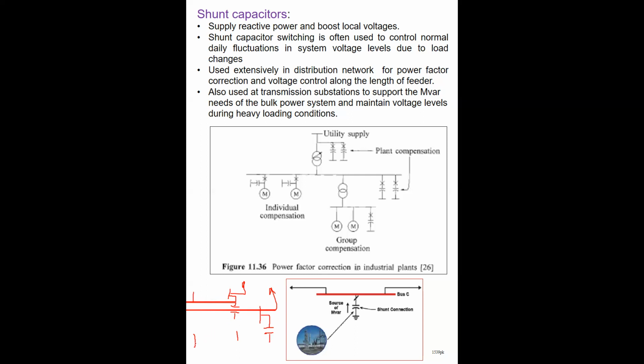For example, if you connect your capacitor here, but your load is here, and you want to improve the voltage at this bus where you have the load connected, with a capacitor connected here, then there is a transmission network connection in between. Then this capacitor has to compensate this much amount of reactive power also through the line. So this is not a good design, in fact.